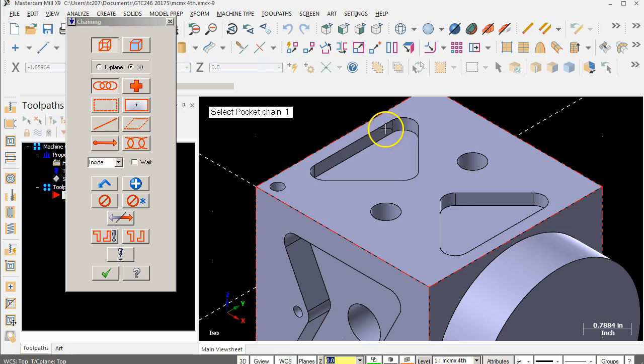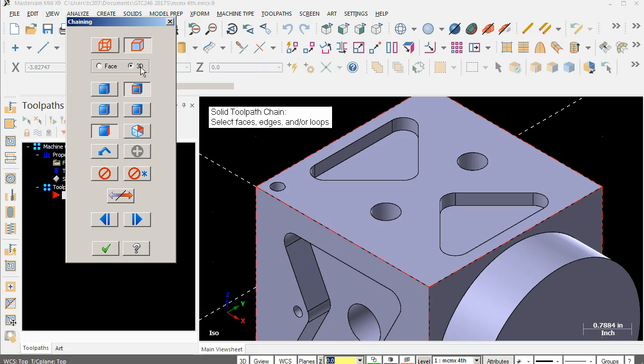So let's see. Oh, and notice that it's not selecting. I always get to this point and why am I not selecting? Where is my geometry? Where is solid? I have to be in solids. Right? If we pick the wireframe, then the wireframe would operate in the wireframe. So the IGES file would have no issue. As soon as we go over to the solids, am I picking into the faces, into the 3D geometry, and then I'm over to loops and partials, edges, and the faces. All right, so now I see things start to select.